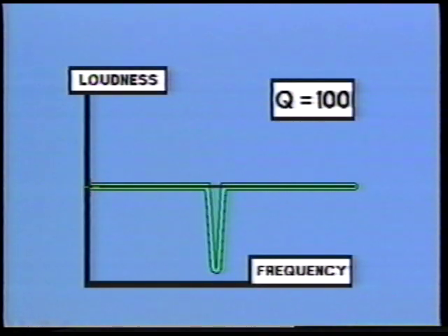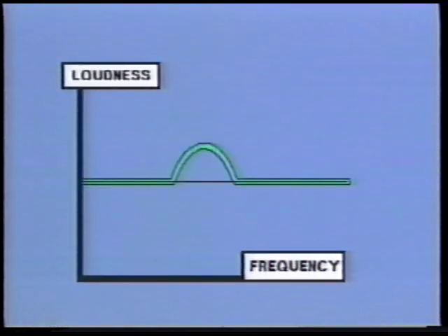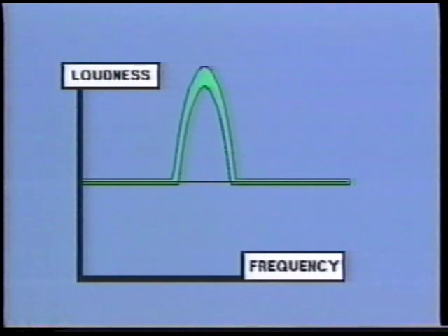An extremely narrow band EQ, a Q of 100 plus or so, is called a notch filter because it dips out a very narrow range or a notch of frequencies. For instance, a notch filter is useful when dipping 60-cycle hum or any other well-defined fixed frequency, such as film camera noise. Remember, Q is independent of amplitude. Whether you turn it up a little or a lot, the Q of the filter remains constant.